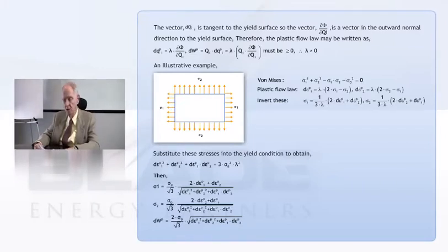Prager works out a little problem and shows it, and this little figure he has is his yield surface, and it's moving around, so he's keeping a constant, he's using a Mises condition. He's using non-work hardening, so he's got a circle, and he says it's incompressible both in elastic and plastic strains.